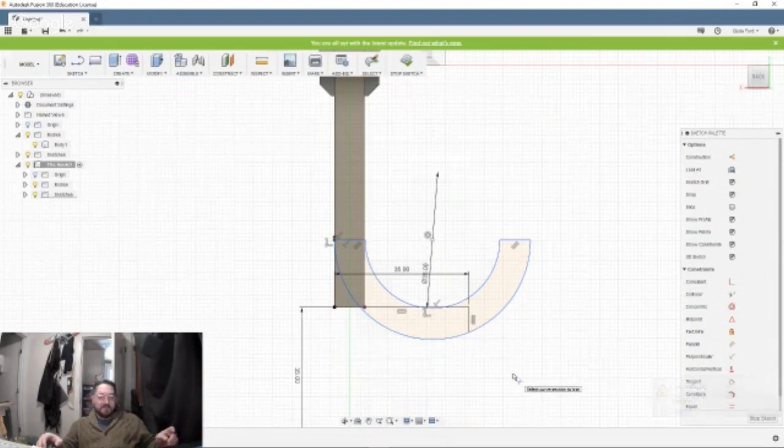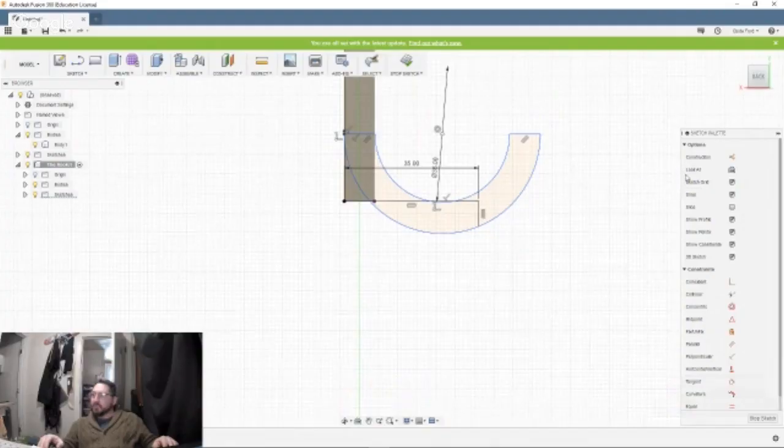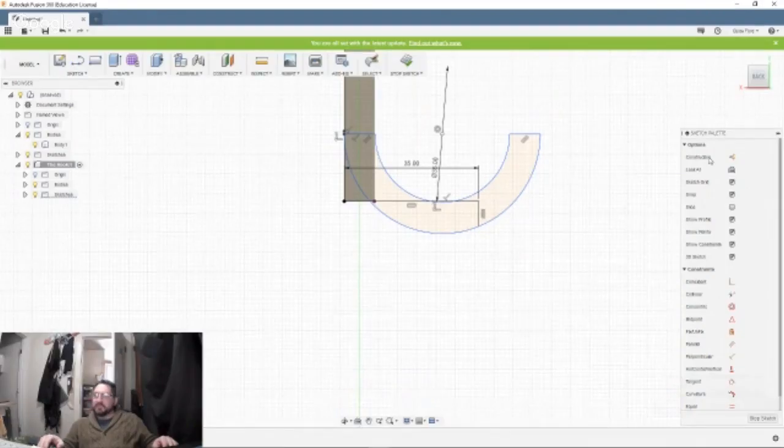You'll see a lot of errors here and there because a lot of those lines were reference lines. If you actually need them, you redraw them. And see up in the right-hand corner of your selections palette? At the very top, it says construction line. If you make one of those construction lines, they don't do anything but be used for measurement.